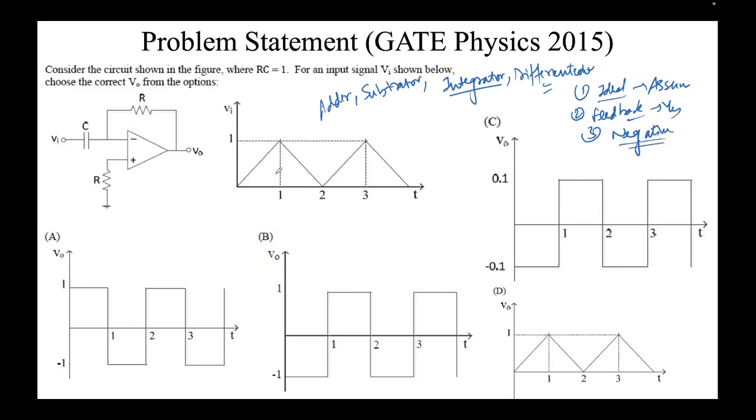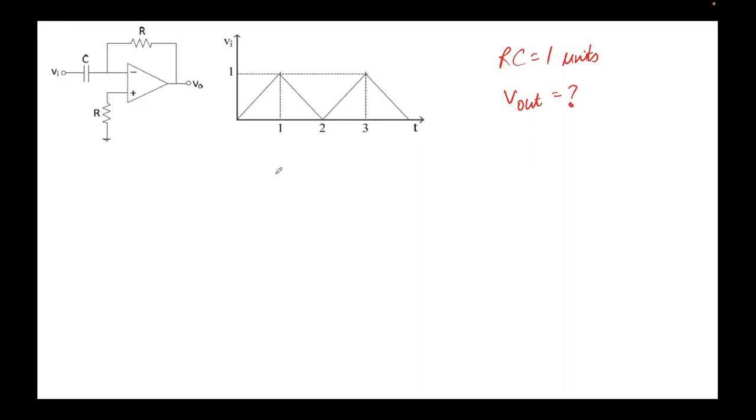Ideal. Let me go to the next slide because there's a space problem here. Okay, so again, ideal op-amp, I equal to 0, I equal to 0, and virtual short means this is same as this. Let's assume this voltage to be, okay, this voltage will be 0 because this is 0, but my practice is I always assume it to be Vx. Coincidentally here Vx is equal to 0 volts. Again, let's write KCL at inverting input.